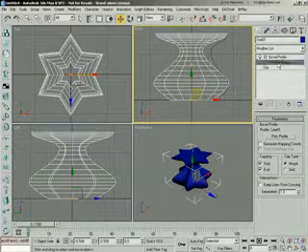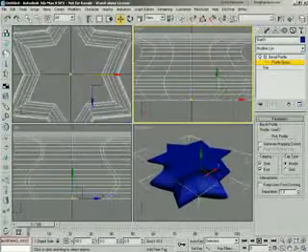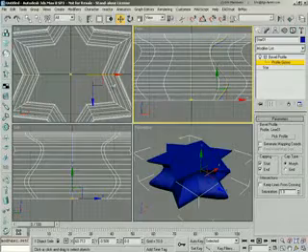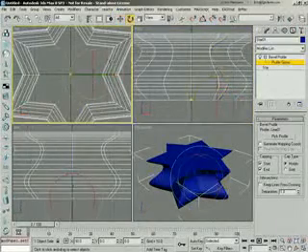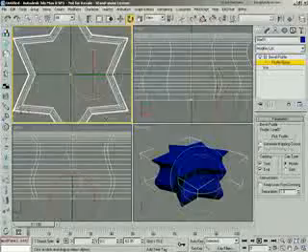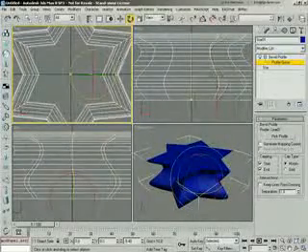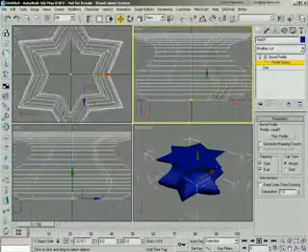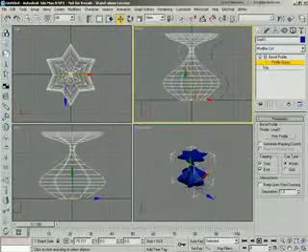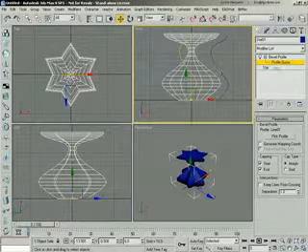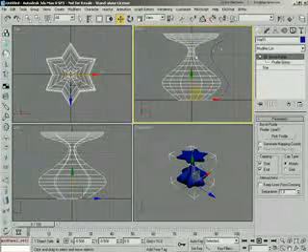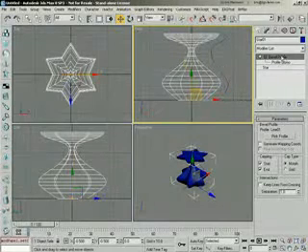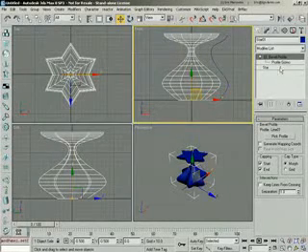So we click on the drop down list, go to Profile Gizmo, drag it out. We may also need to rotate it or position it if we want it to be identical. See, as I rotate it, the effect changes as well. Now, one other thing that may happen is you may find out that your profile isn't exactly right, okay? And you want to go back and modify the shape that it creates. One of the really nice things about Max is that the modifier stack isn't destructive.